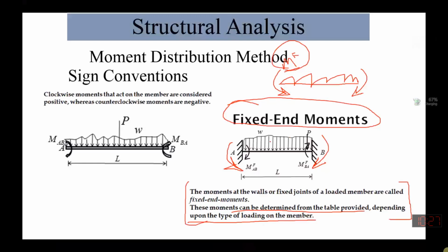Is it clear? Yes, sir. That is how we define our fixed end moment. This is the moment which is generated at the ends of the beam due to the applied load, and it typically depends on the type of loading.